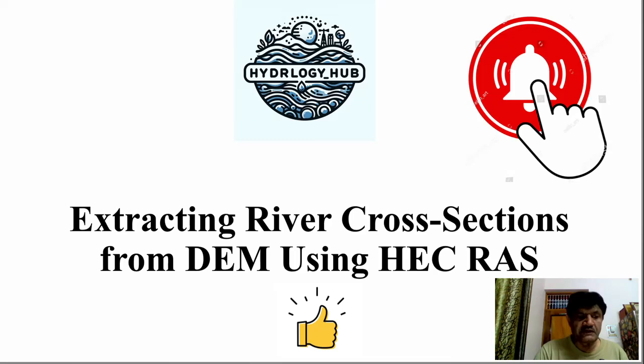Before we get hands-on, let's briefly understand what we are doing. Cross-sections represent the shape of the river channel and floodplain. Extracting them from a DEM allows us to input realistic geometry into HEC-RAS, which improves the accuracy of our flow simulation. Today we will use HEC-RAS with RAS Mapper, and I will walk you through each step of the process.